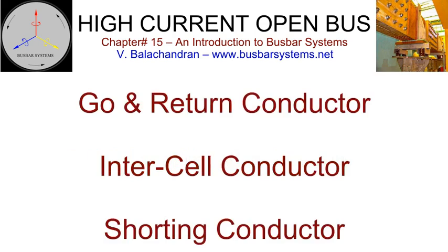The DC busbars in an aluminium extraction plant can be broadly classified as go and return conductor. It is a connection from the rectifier to the first cell and from the last cell back to the rectifier. Inter-cell conductor. It is a connection between the cathode of one cell to the anode of the next cell. To facilitate ease of disconnection, this section comprises a rigid bar welded to a laminated section with a rigid tab. Bolted joints need to be kept to a minimum. Shorting conductor. It is a rigid bar for bypassing a cell.